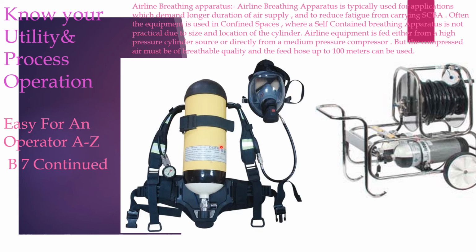Wherever the atmosphere is having a known hazard, you have to use the airline breathing apparatus, whether it is confined space or open space also, because you know the hazard is there, it will be present and anytime it will harm your breathing. So airline breathing apparatus is to be used in that condition.